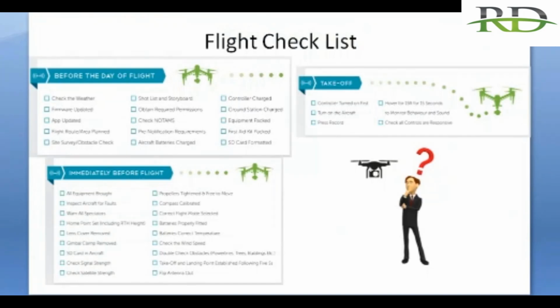Yes, we have to fly the drone. This is very important. There are some steps. First, you have to check the red zone, green zone, and yellow zone, and also the condition of the weather. We also have to check the drone parts and the RC, everything. These are some precautions, a checklist that he has to observe.